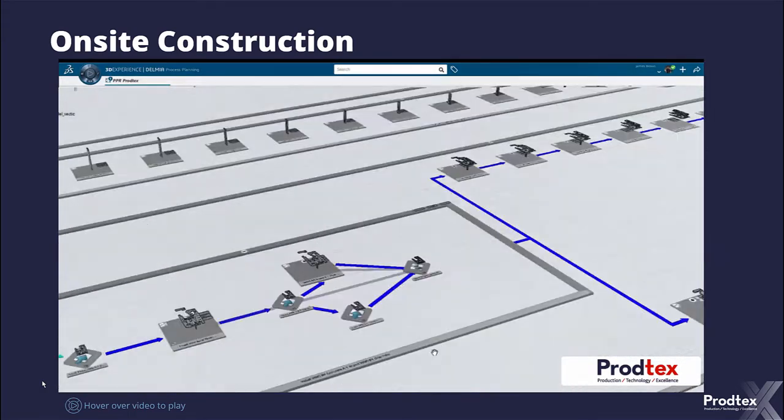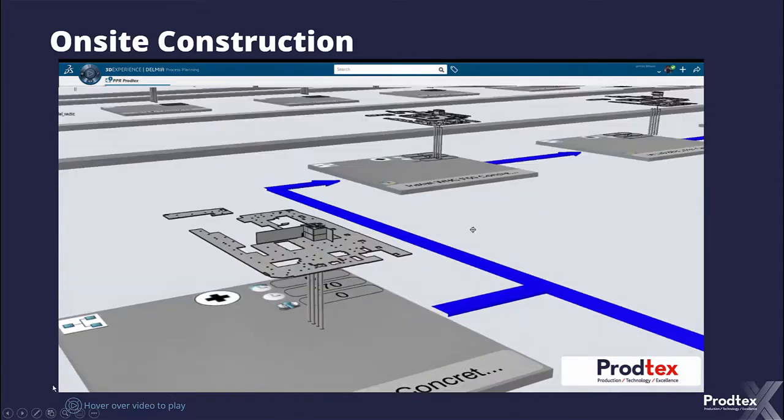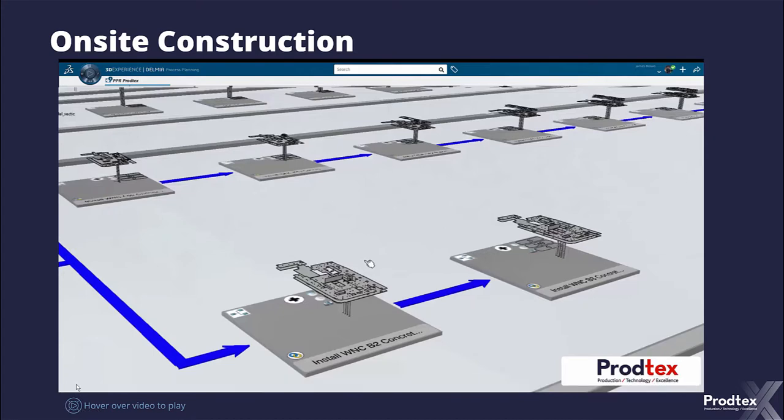without affecting the architecture structure. And then from that, I'm then creating a process plan where I'm actually going to define what floor comes when. So if I'm going to build the first 3 floors and then I'm going to kick off my MEP teams, or maybe it's down to the specifics of I'm going to do this wall, then this wall, then this wall. So that sort of level.